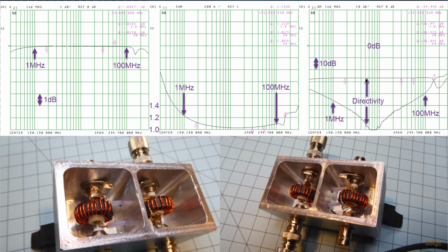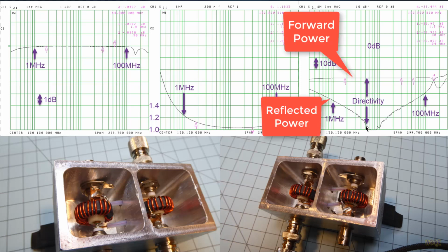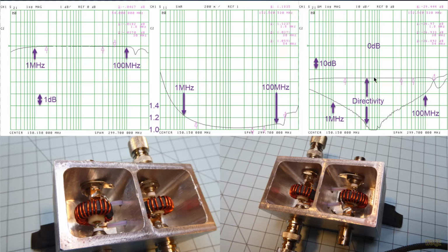And this is the directivity. Directivity is putting power in one direction through the bridge and having a perfect termination on the output and seeing what difference the two powers are on the coupled ports. And when the directivity is very large, that means the circuit did a very good job of getting all the forward power to the forward port. This is the coupling, 26.9 dB. So it couples very flat.